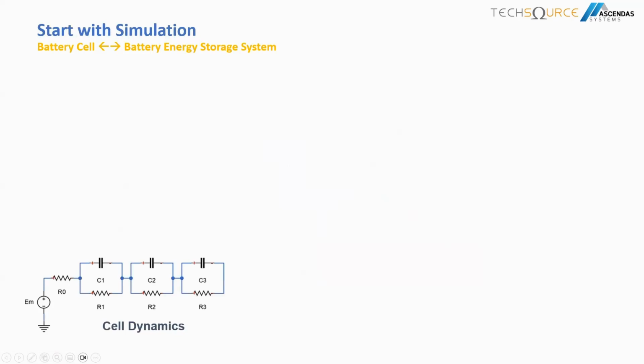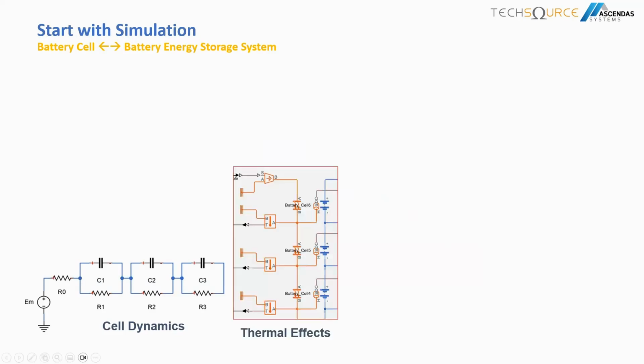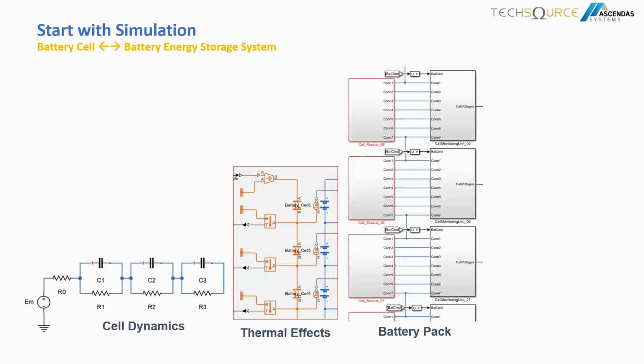So we have changed the parameters. Now let's say we are confident that we have developed the cell model near our actual responses. Then we add thermal, aging and fault dynamics. Then we evaluate certain series and parallel counts, or cell configuration, to meet your capacity and efficiency requirements, and you design your battery pack itself.